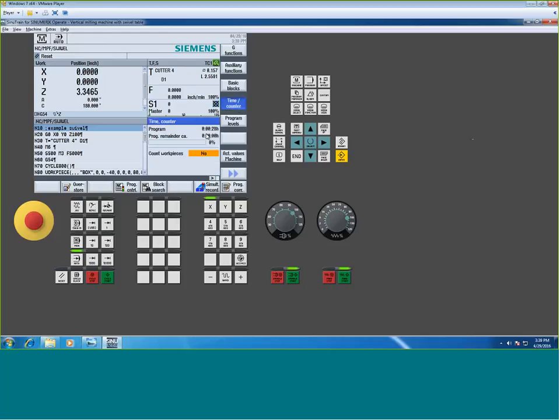I have done testing in Sinutrain on a machine tool that was heavily optimized by our engineering group, and I ran cycle time tests on programs that were taking an hour, hour and a half to run. I'd run them virtually in Sinutrain, and then I'd run them in real time, and on an hour program, if there was a 5 or 10 second difference, it was a lot, and a lot of that I attributed to just throttling back my override when I was leading into cut. I mean, it's right there. And again, it's taking all the drive parameters into account. That's why it's critical to have the drive parameters when you build the machine.